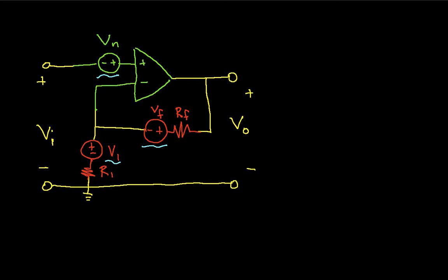It turns out that doesn't work. What we want to do is find the output voltage for each noise source in turn. And because they're noise voltages, when we get this RMS value, we will get the total output noise by summing the square of each of the RMS voltages and then taking the square root of that. So that's what we will do.